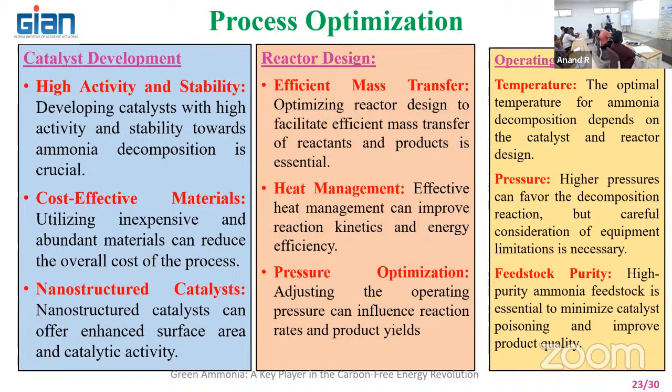Then the reactor. The reactor needs to be designed so that there is not much loss of energy, heat loss from the reactor. That's why we said microwave is going to be better than other types of process, because heat is generated inside. The heat loss is going to be from inside to outside. So the system is highly insulated, so the heat loss is going to be minimum.